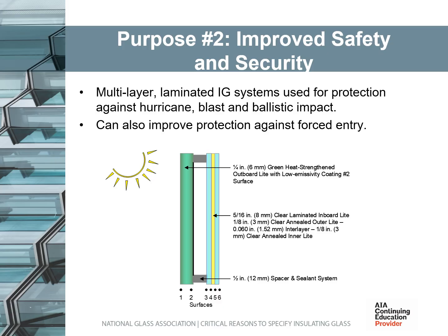Laminated glass's most important characteristic is the ability of the interlayer to support and hold the glass when broken, and/or plastic sheet when cracked. This provides for increased protection against fallout and penetration of the opening. Most building codes require the use of laminated glass for overhead glazing as monolithic lights, or as the lower light in multiple glazed units. Other applications include safety, security, detention, seismic resistant, blast resistant, bullet resistant, burglary resistant, hurricane cyclic wind resistant, and sound reduction applications.